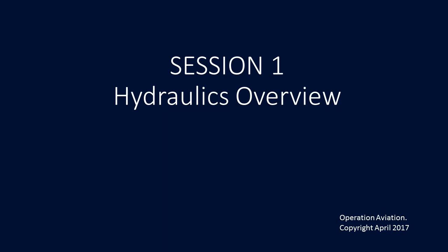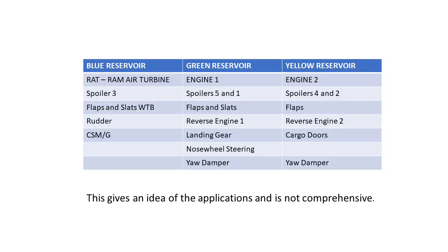The applications that are not used in flight, those are separated out from the main supply of power. Now, what about the auxiliary generation systems? Okay, the auxiliary power is actually coming from your PTUs of the green and yellow system, the RAT of the blue system located in the left belly fairing, and then the electric and hand pumps of the yellow system, and those are located on the yellow ground surface panel. The hand pumps in this system are used to operate the cargo doors in the event that there's no electrical power. So let's go ahead and just take a look at the diagram.